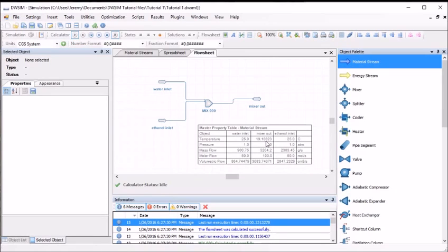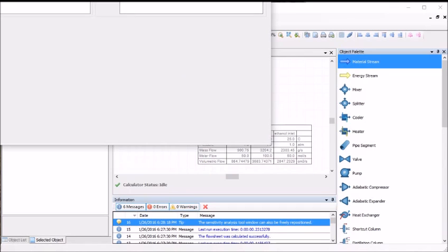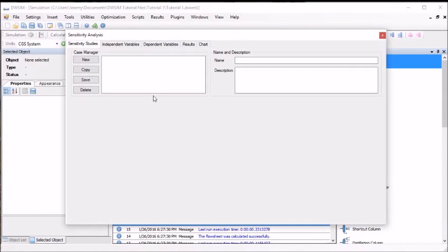So we will use the sensitivity analysis tool to see if changing the molar flow rate of ethanol into the mixer will change the outlet temperature. This will not validate our results, however, it will let us see if the Lee-Kesler enthalpy calculation method is predicting an endothermic heat of mixing throughout the entire range of different ethanol water molar feed ratios. To do this, click on Optimization and select Sensitivity Analysis. The Sensitivity Analysis form should appear.